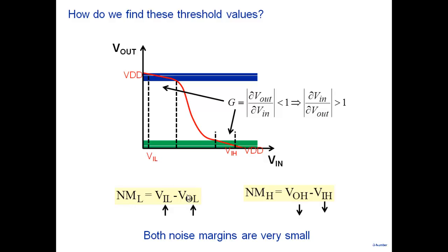So up to what point can you keep on doing this? Well, you can say increase it even more. This will also increase. This will increase even more than this. Noise margin will further increase. At what point can you keep on increasing? Can you all see that this will stop when the gain, wherever you reach, becomes equal to 1. You can keep on decreasing VOH or keep on increasing VOL till you reach a point where the gain is equal to 1. Because this is the basis for why noise margin is increasing.